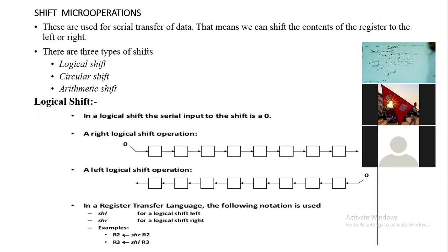Discarded. Okay, this is left shift. And what will be the output? The output is 0, 1, 1. After performing logical left shift, what will be the output? This is the output, 0, 1, 1, 0. 0 is inserted at the first position, the next bits are shifted to the left by 1 bit, and the last bit is discarded. Okay, in this case we have to lose our data like this.